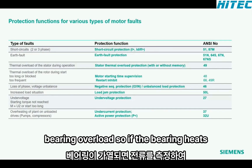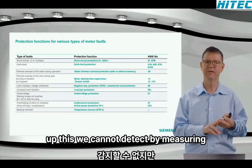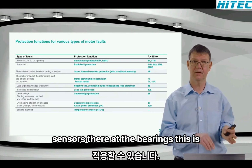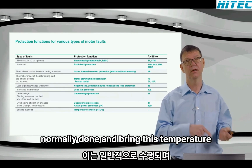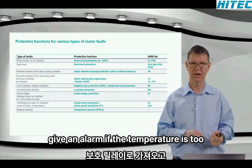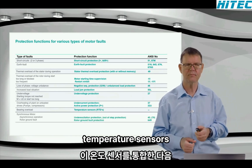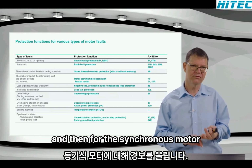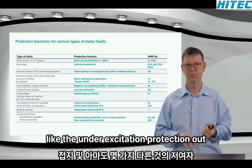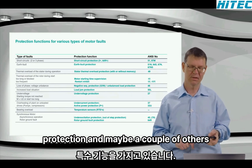Bearing overload: if the bearing heats up, we cannot detect this by measuring the current, but we can apply temperature sensors at the bearings. This is normally done, and we bring these temperature sensors to our C-Protect relays and give an alarm if the temperature is too high, so we can integrate these temperature sensors. And then for the synchronous motor, finally, we have some special functions like the under-excitation protection, out-of-step protection, rotor ground fault protection, and maybe a couple of others.